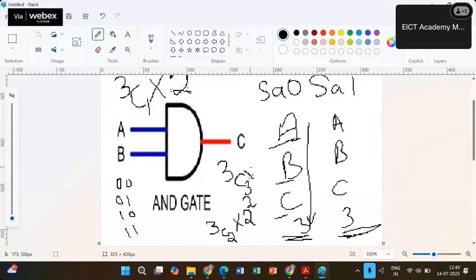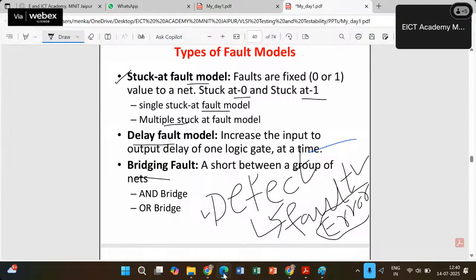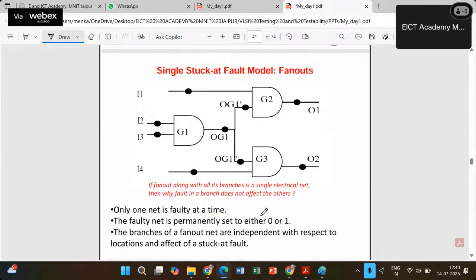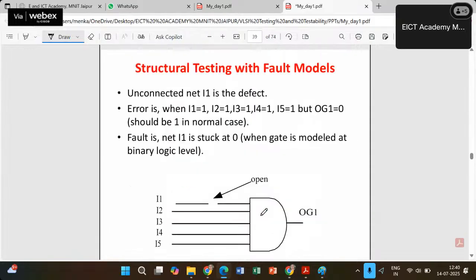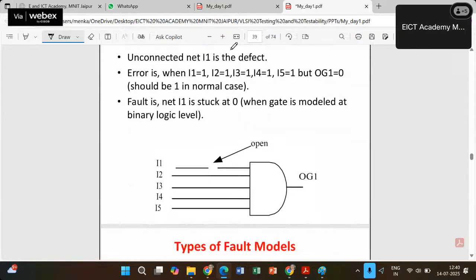And we have to multiply this with how many patterns of 3-bit are possible? 2 raised to power 3. So adding all these together, we will be having the total number of faults, which are single stuck-at faults and multiple stuck-at faults altogether. So to figure out how many faults we can have, let me do the calculation over here. Let me take this rough base.